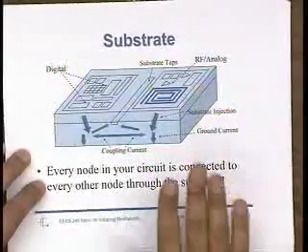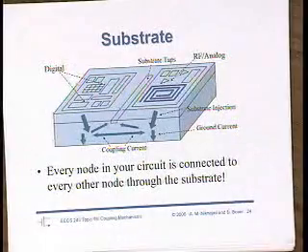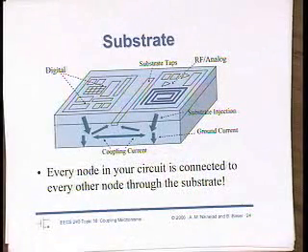All right. So that takes care of package coupling, supply coupling, coupling through your leads. It gives you a good idea what to do to take care of your ground connections. But at the end of the day, you do all that stuff, and you still have your nasty substrate, right? So we've got to live with, you do all this good stuff on the outside, and you cut down the noise, but ultimately, all your circuits are sitting on the same substrate.